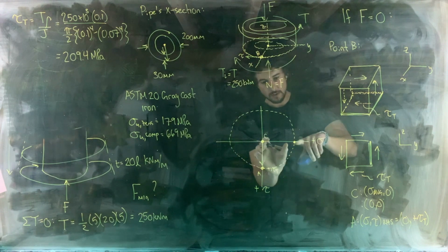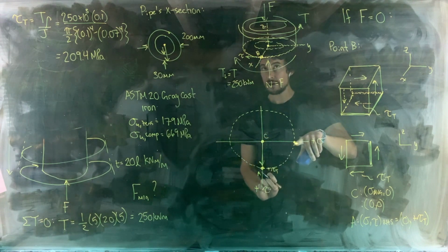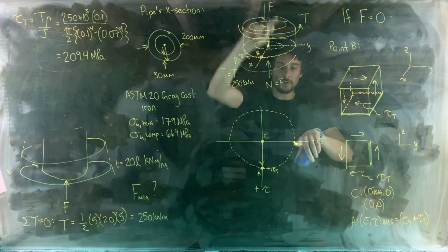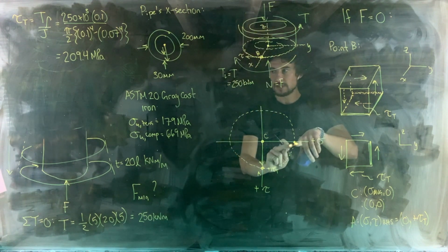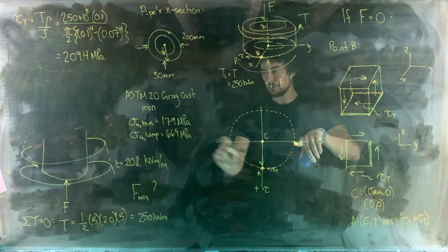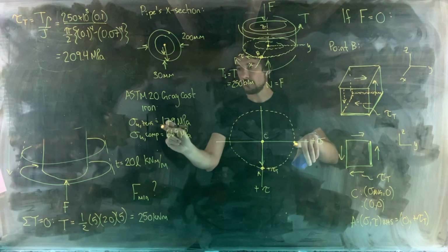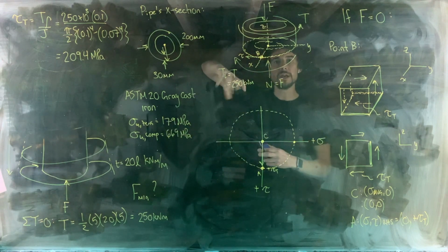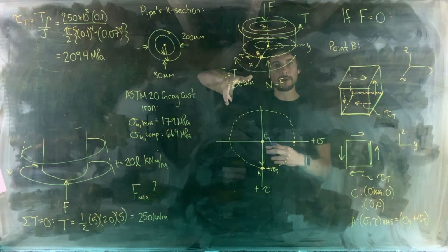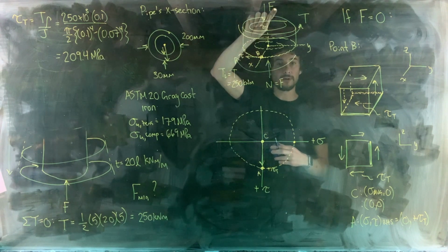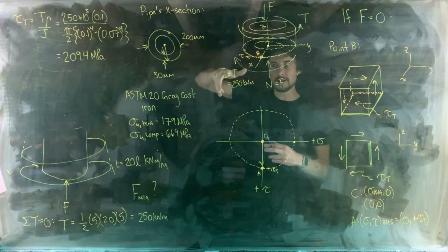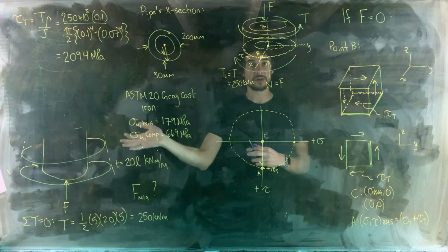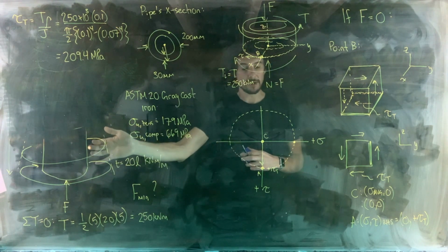So the tensile stress there, if the compressive force is 0, is going to be 209.4 megapascals. That exceeds the ultimate tensile strength. So we could not rotate that pipe just by applying a torque without a compressive load. The pipe would break before we overcame the frictional resistance to rotation applied by the soil.